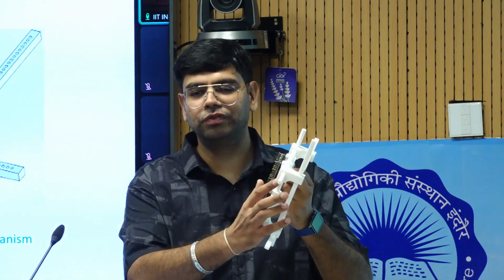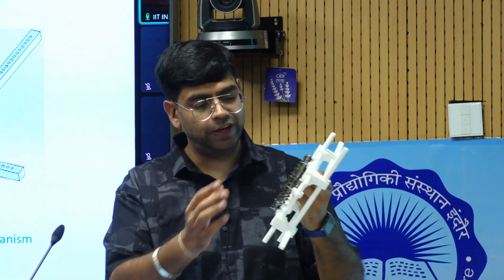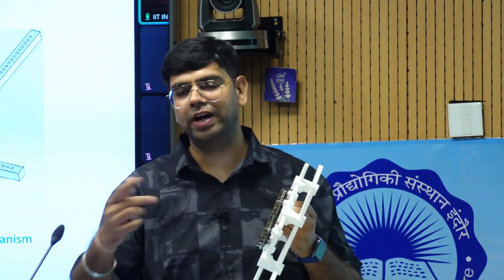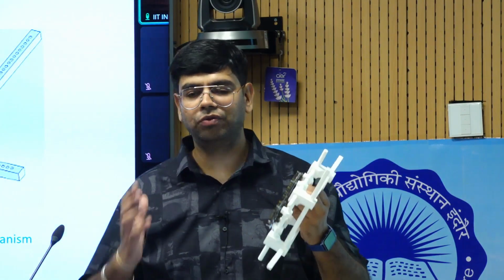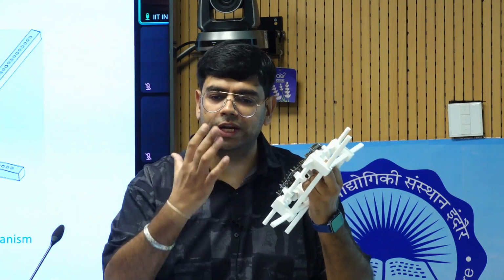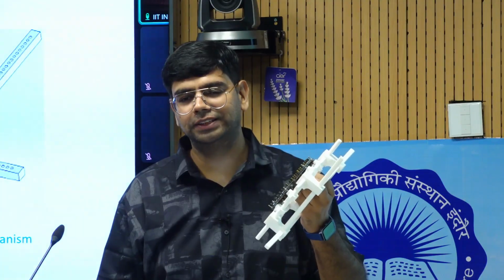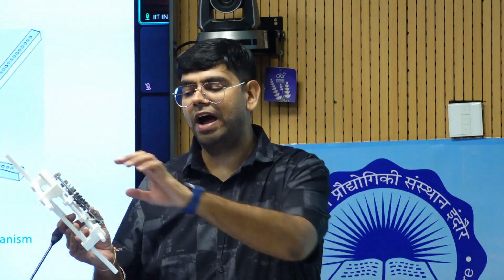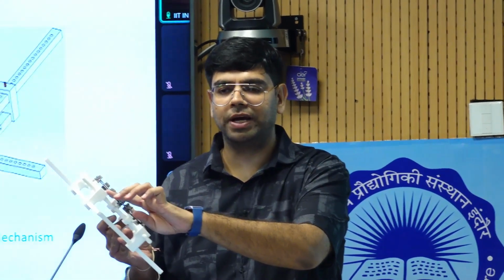If we are using it for the larger pre-stretch, it's very difficult to hold that. So you have to design this thing. When we are designing in the CAD modeling, we have to look at whether, if we are providing a very large force to that, it is holding that object or not. So that is the required thing. So his question is right. If we are going for the larger pre-stretch, we have to design this stretching mechanism.